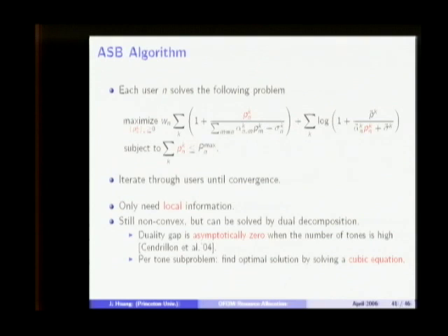You can measure the serial line day by day, month by month, year by year, and you accumulate enough data, and you know typically what kind of crosstalk it is experiencing, what kind of background noise it has, and what kind of power it's operating on. And use that, because this is a time-invariant interference channel. So you can use the fixed parameters for this fictitious line and achieve good performance. Of course, it changes depending on night and day, but it's not changing every second.